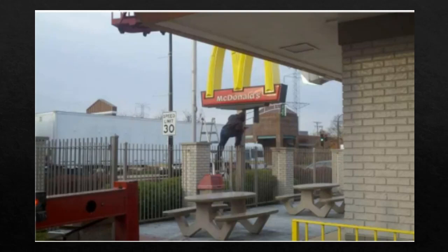And if they were to slip, if that ladder was to kick out, which it could very easily do, they're going to fall right on that fence and become impaled. So, never ever overreach when you're on a ladder. Come back down, reset the ladder, think about different ways of doing it. Never overreach on a ladder.